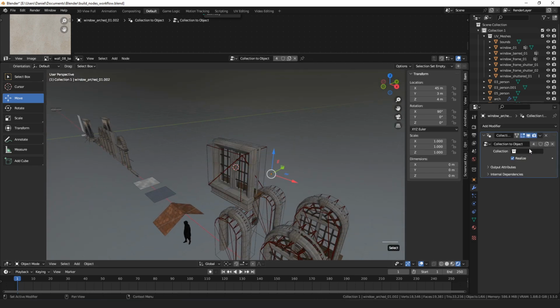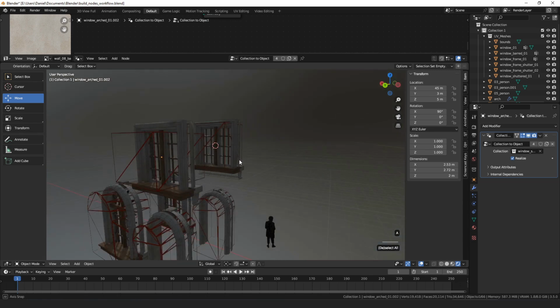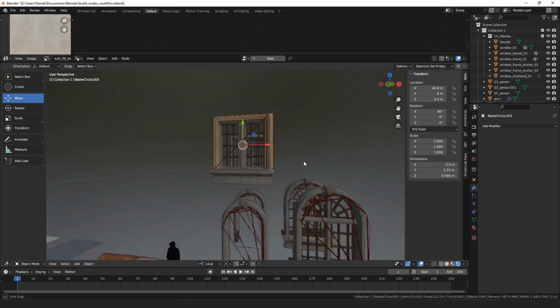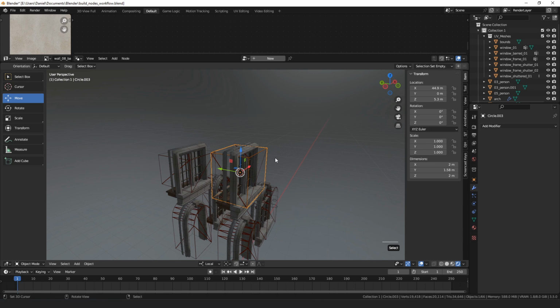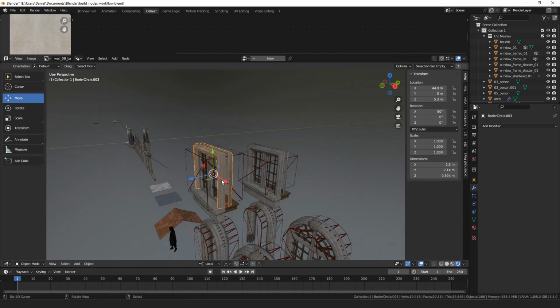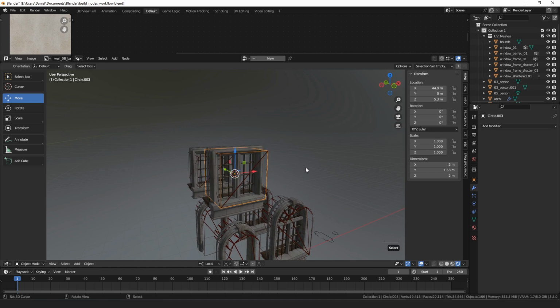So then on this object here, we'll select the window square as our target collection. Make sure everything lines up correctly. One thing to note is if we look at the local on this, because I copied everything. Oh, so this one's wrong. So I copied everything except this box I added. So you can see in their object orientation, the z-axis points forward, and that's important because if you use instance on faces, the normal of the face will be matched to the z-axis.